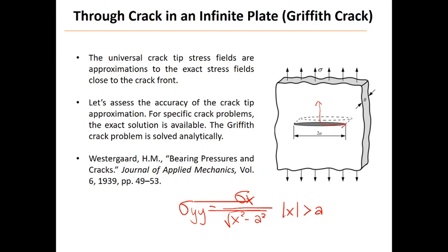So this is the coordinate system. The solution in yy means that we're looking at this stress, sigma yy, along the line in front of the crack. We're going to compare that solution to the crack tip stress field by Williams.